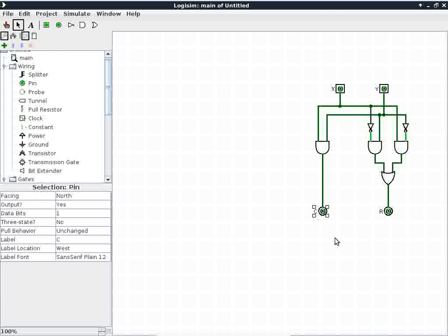All right, so I have a half adder already specified here. Before I turn this into a component, because I don't want to have to copy and paste these things like 8 times for a half adder, what I'll do instead is to test this first. If this works out, I'm going to turn it into a component. Once you turn it into a component, you can make instances of that component. It's kind of like creating a struct in C++ programming. Once I have a struct, I can have instances of that struct itself, or I can put that struct into another struct for hierarchical design.